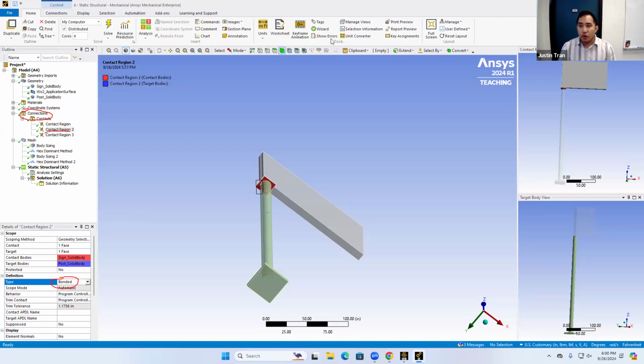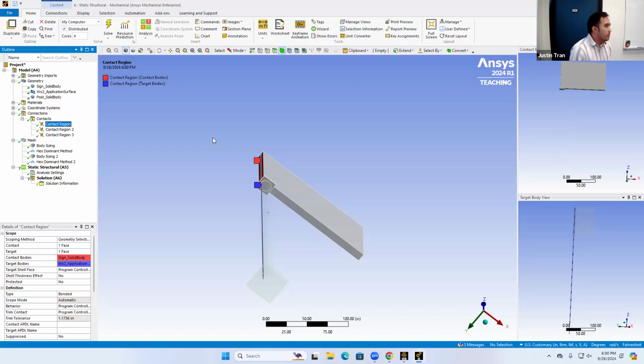One other thing that can be useful, and I know some of you have already been doing this, is that you can rename some of the objects that you have here. To rename something, you click on that object within the project outline and then hit F2 on your keyboard. Renaming is not a requirement for anything. ANSYS will automatically determine names for you, but it's useful for your own organization to rename the parts, connections, or boundary conditions to something that makes sense to you.